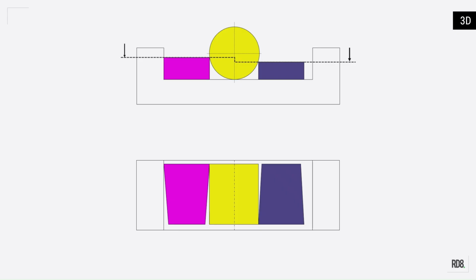3D stacks are complex to handle and close to impossible to review and verify. Complex tools like 3DCS and CETOL are needed for 3-dimensional stacks. However, most stacks can be handled in 2D, especially if applying robust design principles. How can you apply robust design principles here? Consider whether you can avoid non-perpendicular contacts, and design interfaces that are easy to define.